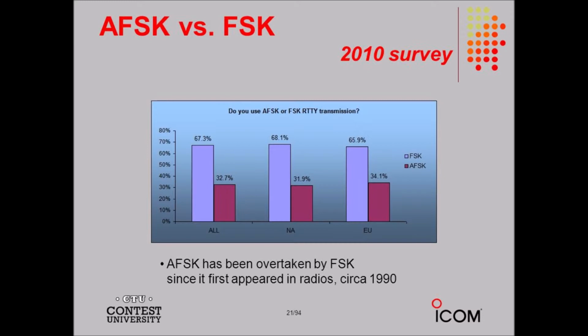We can express the modulation extent as a percentage ranging from 0% representing an unmodulated carrier to 100% representing the maximum possible modulation we can get without distortion. If we increase the modulation beyond 100%, we observe the same problems as we do when we apply excessive AF input to a modulator circuit, such as the one shown in figure 25.2. In an AM signal that's modulated at 100%, we find that a third of the signal power conveys the data, while the carrier wave consumes the other 2/3 of the power.